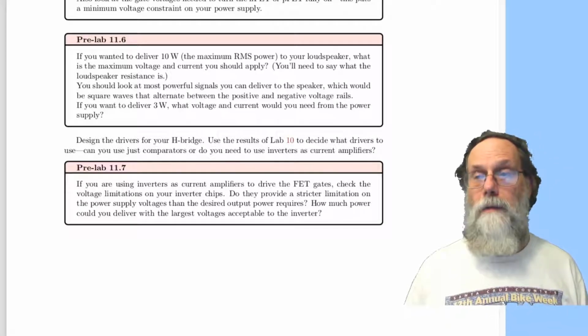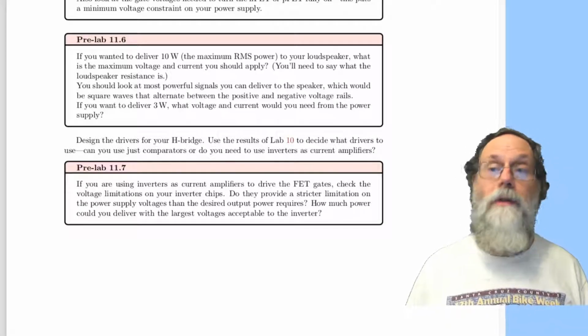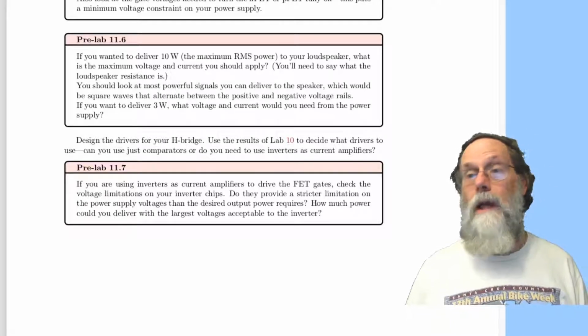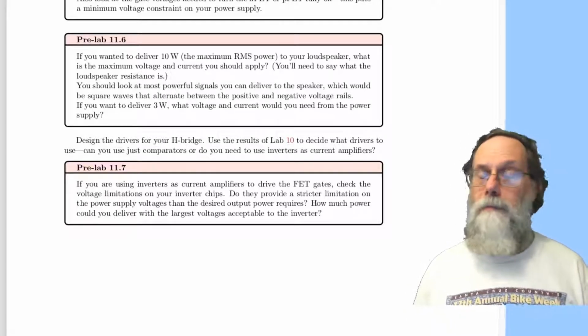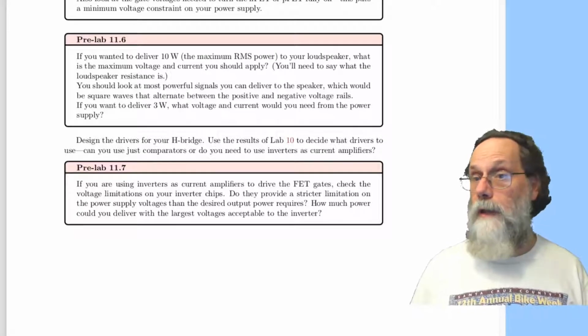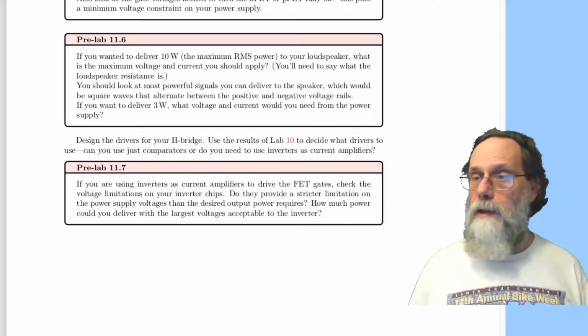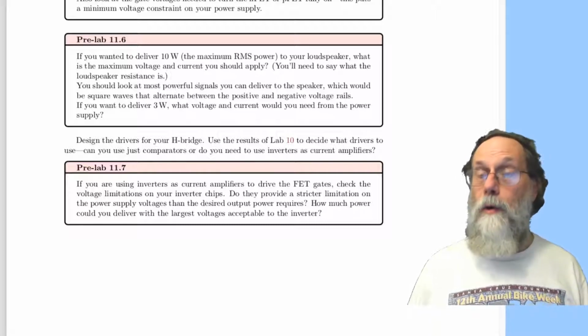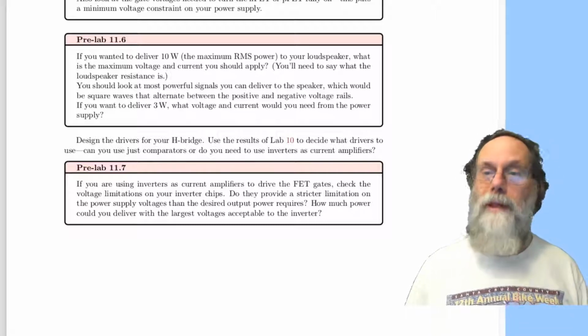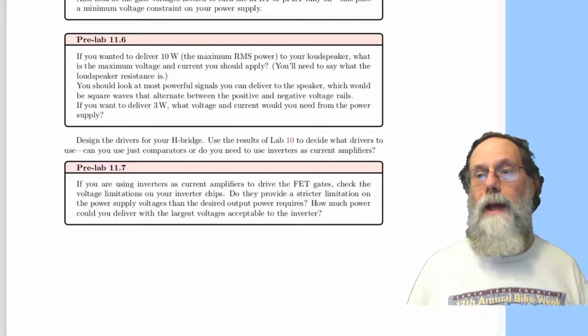Okay, you've got comparators probably, you've got your preamplifier which has got op amps in it, you may have some inverters in there to act as digital amplifiers for the PWM signal. What are the limits on each of these devices? What limitations do those put on your power supply? Make sure that everything is consistent and document it.